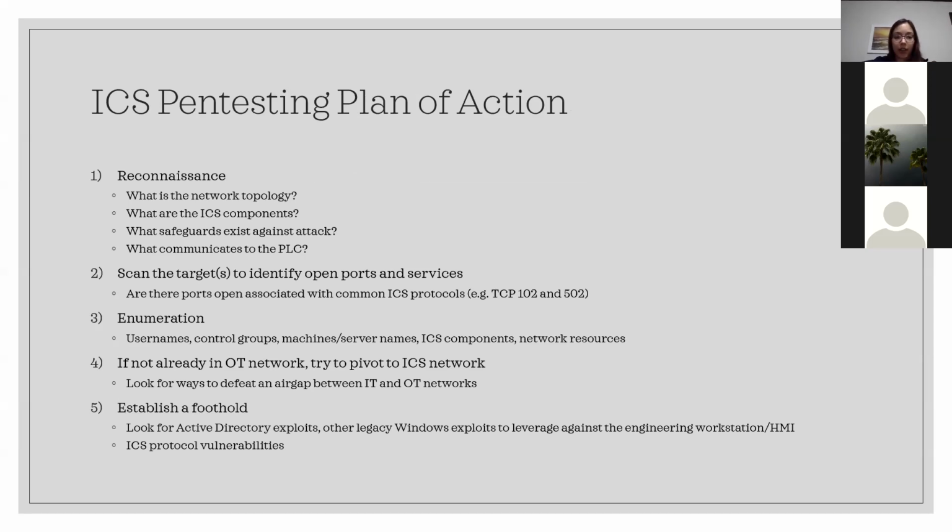Specifically, you want to know what the network topology is. You need to know what sort of ICS components you're dealing with. Are you dealing with a distributed control system? Do you have some PLCs on there? What kind of PLCs do you have? What communication protocols are they using? Is the IT and OT network properly segmented?